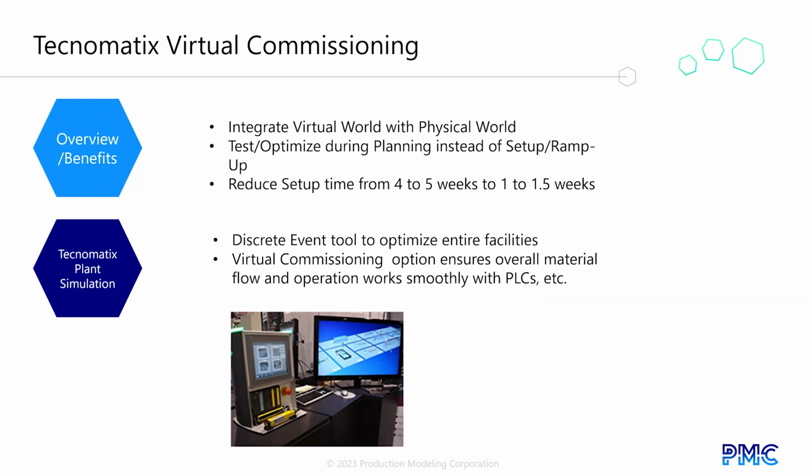The photo shows a typical setup. On the left is the control panel for the PLC. On the right is the plant simulation model. This is an ideal setup since the PLC is not yet connected to the plant floor, so you can check out and tweak your control logic virtually before going live in the plant. With the PLC Sim Advanced interface, you can even interface with Siemens Virtual PLC that lets you check out control logic without the hardware.